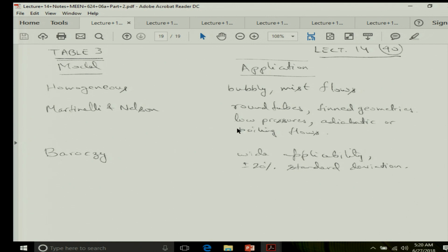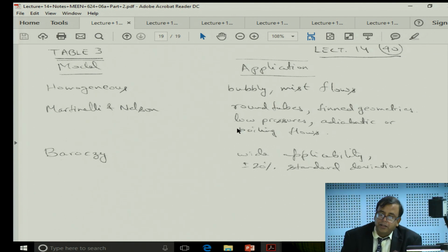Okay. So, now that I have the pressure drop part figured out, the next part is figuring out the heat transfer. Now that I know what size pump I need, pressure drop times your flow rate gives you the pump power, and then you assume your motor has a certain amount of efficiency, and you divide your theoretical power by the net efficiency to get what kind of pump motor you will need. So, the pressure drop part is calculated. The next part is how long a pipe do I need, for a given flow rate to go from pure liquid to pure steam.